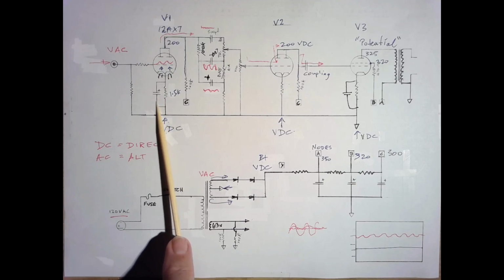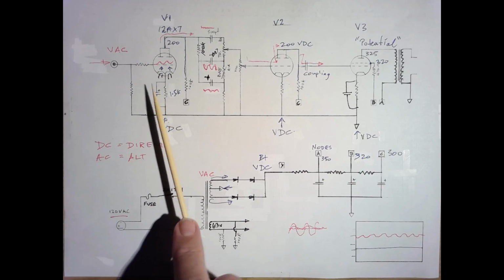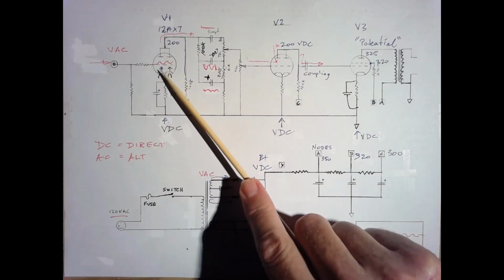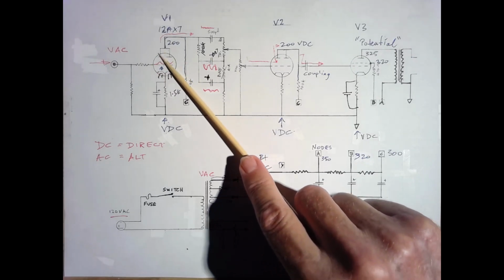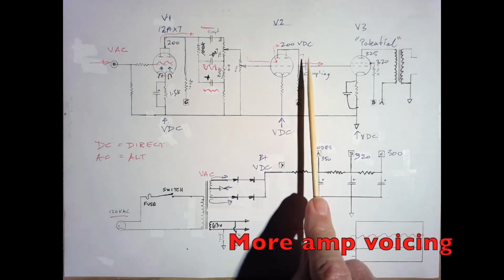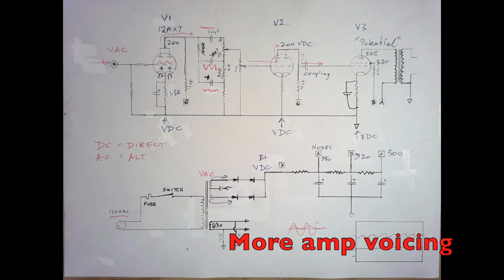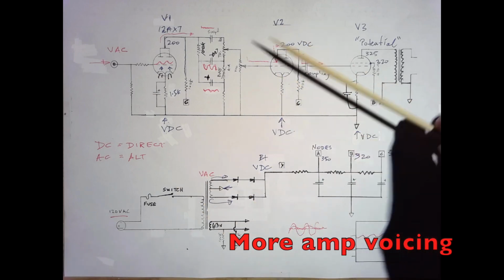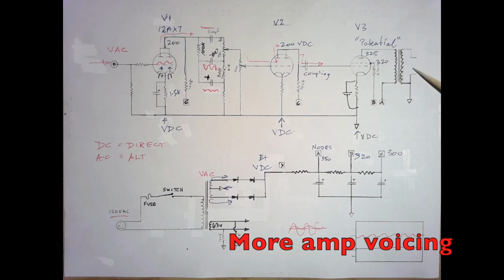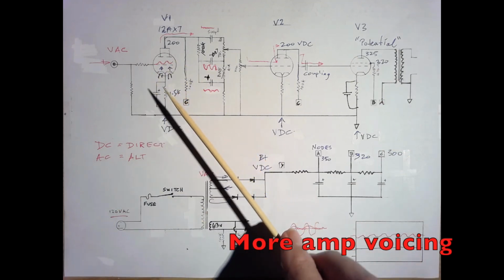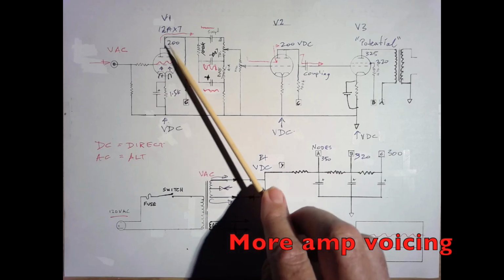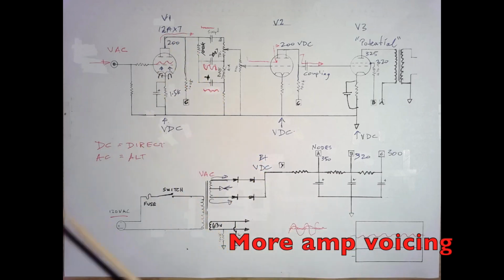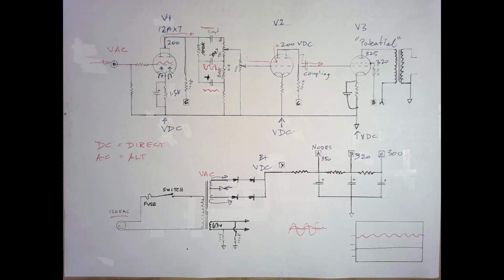But if you have a big capacitor here, you allow a lot of bass movement to go on in the signal, passing it through these stages. And typically for an overdrive stage, you don't necessarily want a lot of bass because it will make the outcome kind of flubby at the end. So basically you can dial all that down to just being mid-range gain or treble gain or whatever you want, rather than having bottom end gain, which can get very muddy and not sound so great.